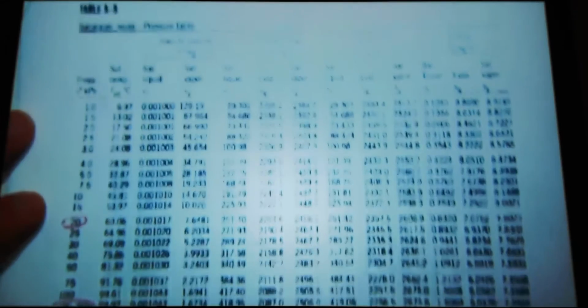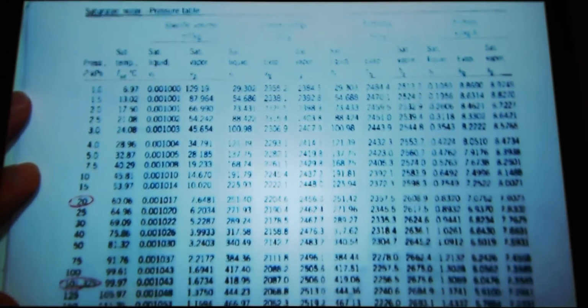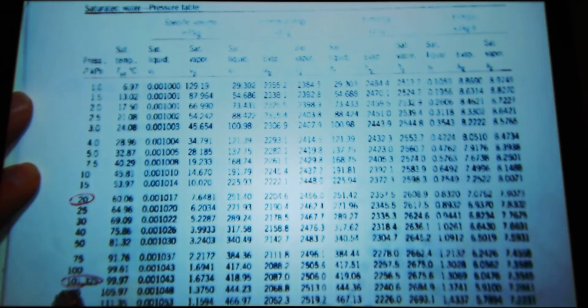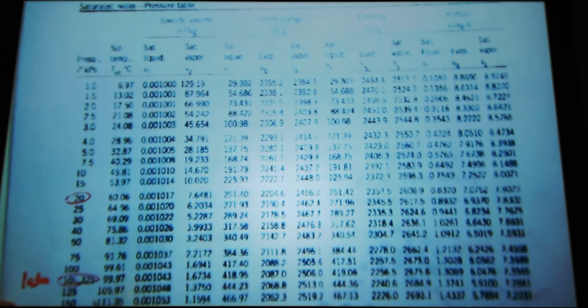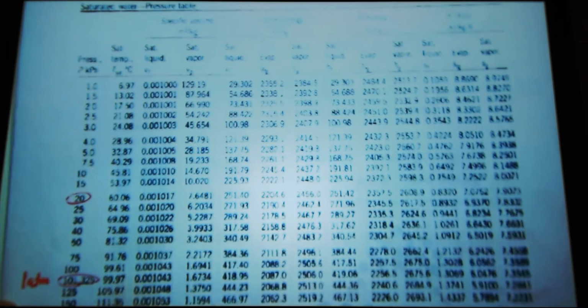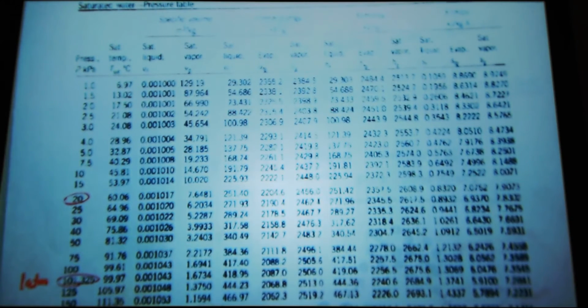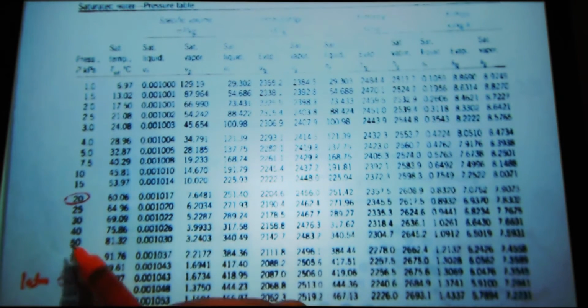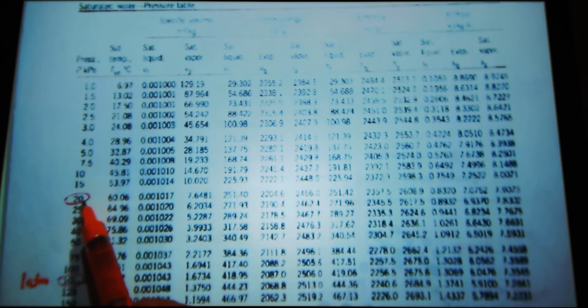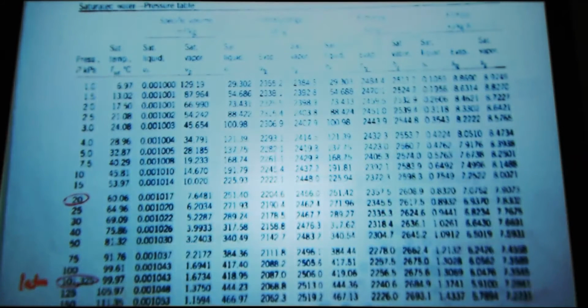Now this is a pressure table for saturated water. So now I list the saturation pressure. 101.3 is 1 atmosphere, and the saturation temperature is 99.97. So pure water at 1 atmosphere really boils at slightly under 100 degrees. If I reduce the pressure, so I go to the top of Mount Everest, the pressure there is about 20 kilopascals. Water boils at 60 degrees C. What is our body temperature in Celsius?